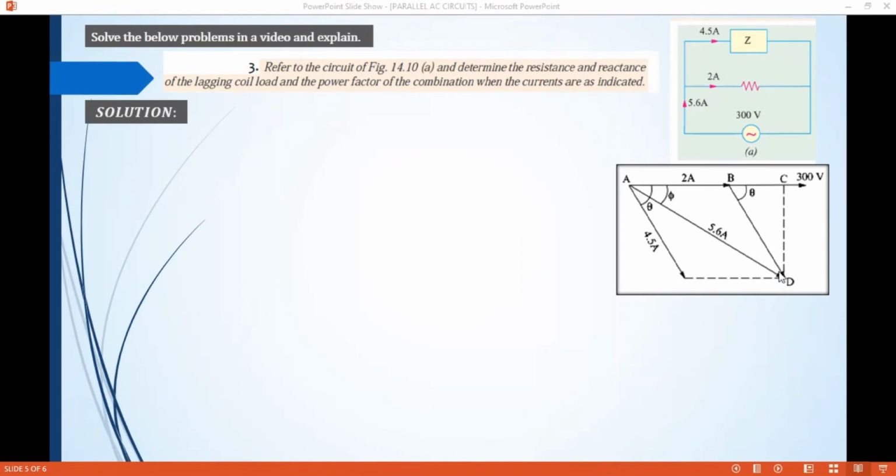it stands as the resultant in the parallelogram figure. And then here our broken lines form this as a parallelogram. So we have our phi and our theta. The formula for this one is from the parallelogram law of forces: the resultant squared is equal to a squared plus b squared plus 2ab cosine theta.